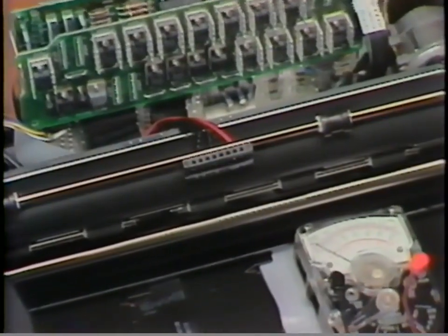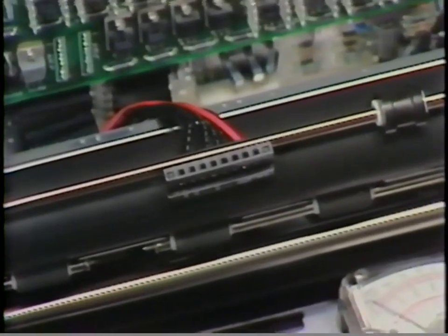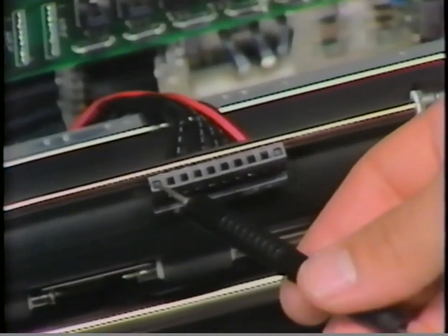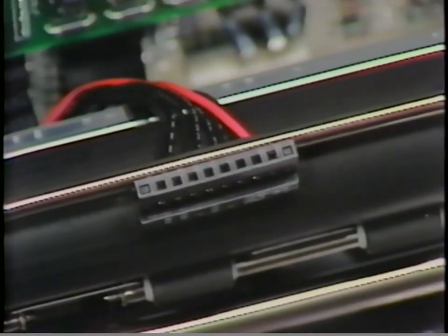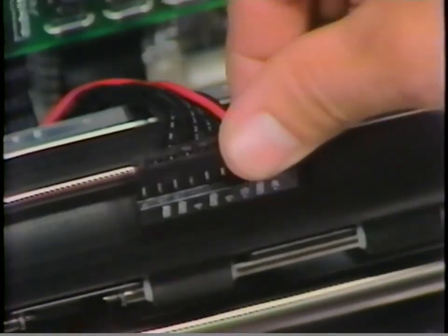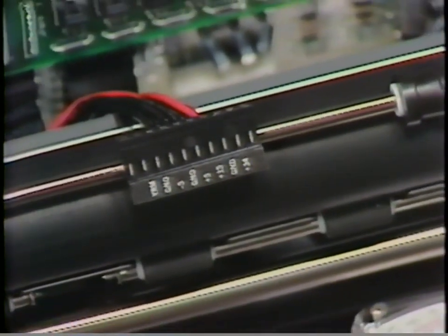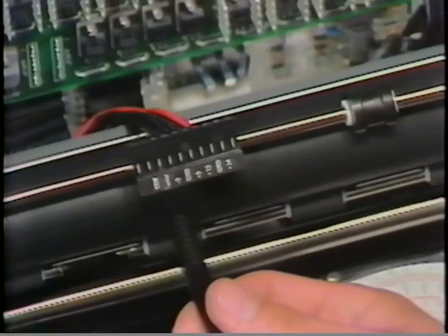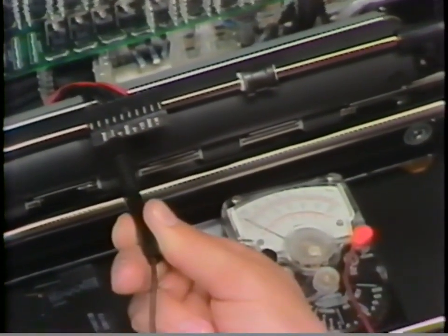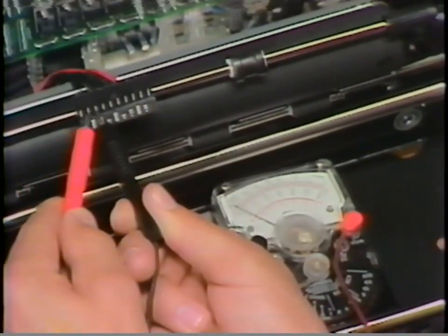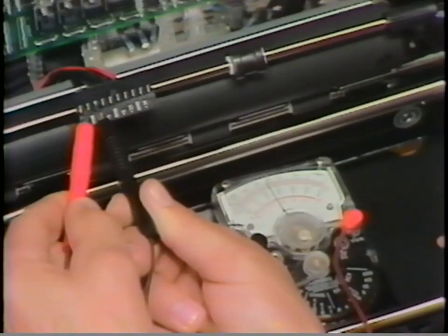J6P has a blocked pin at each end of the connector to ensure that the connector will be plugged onto the board correctly. These blocked positions are not counted in the pin numbering system. When taking power supply readings with the power supply connector J6P disconnected, you must use the power supply ground on pin 2 of the J6P connector. The reading from power supply ground to the VRAM signal should read 4.6 to 5.6 volts DC.